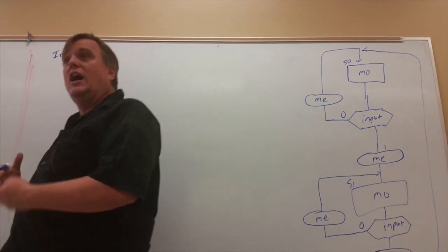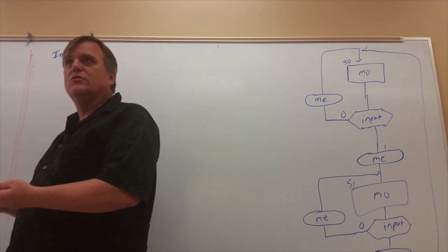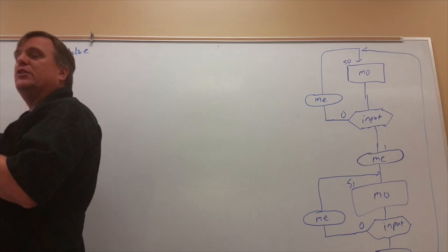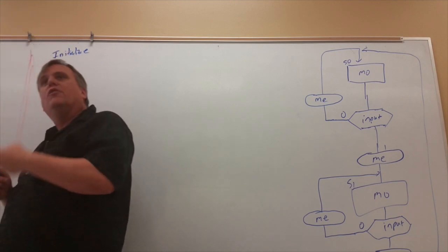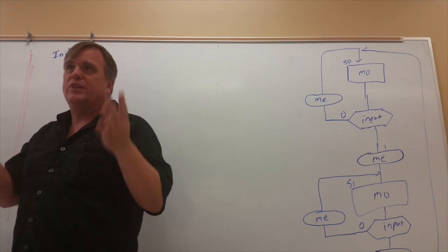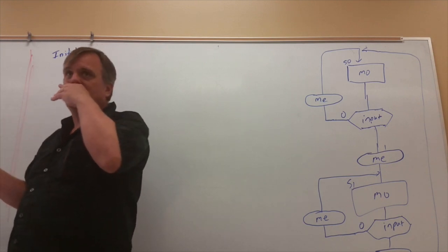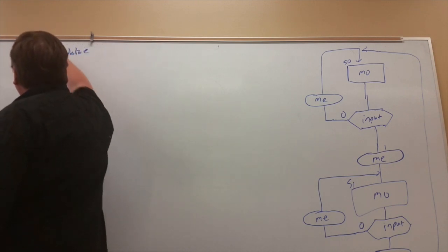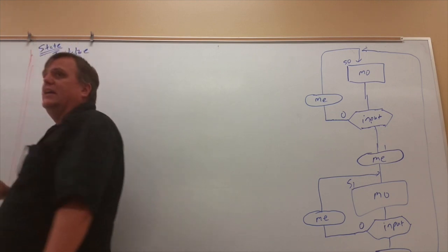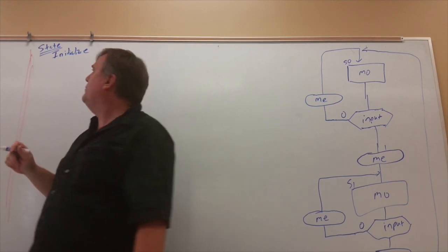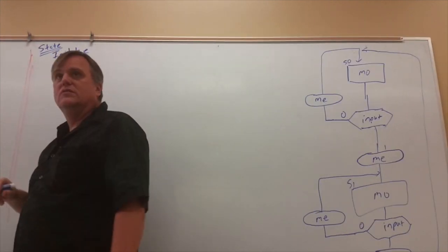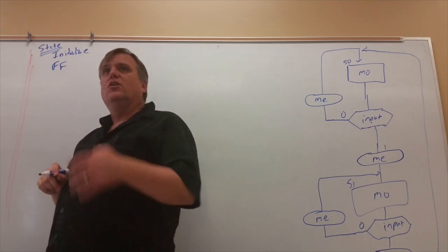Okay, so now I actually have to have variables. Right? So I'm going to therefore have something that's not just, for my program that I'm going to write in Verilog, but it actually has to generate memory that has to actually exist. So I'm going to have state. Right? That state is going to imply flip-flops that have to be initialized. All right? What else do I have?